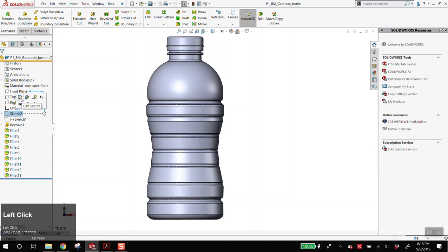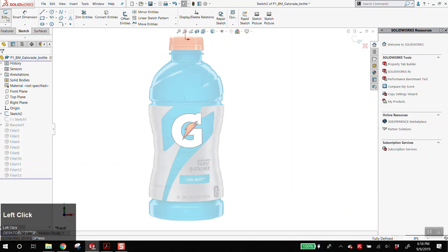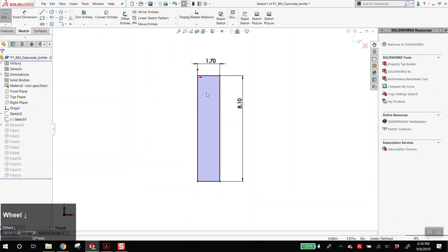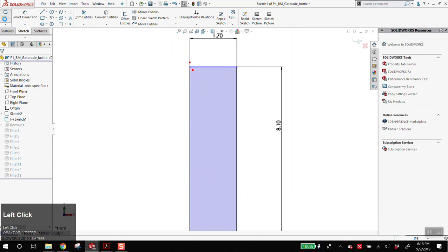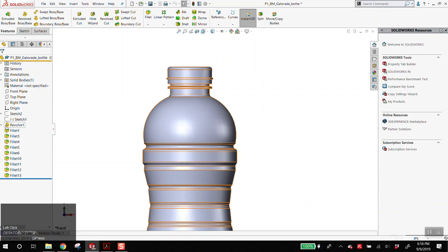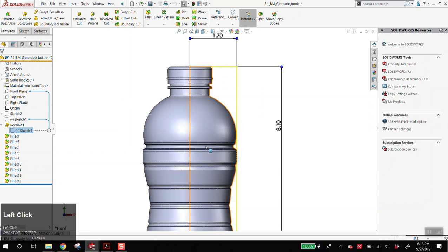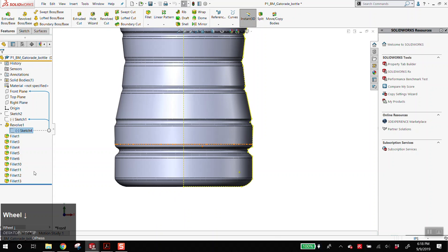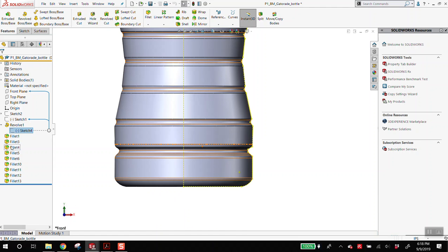So, okay, just a quick overview on everything. You got the sketch in there, looks good. Master sketch, are you on the origin? You are. Again, here's an instance. This is the same thing that Alec and Juan did, where you have the bounding box as your master, when really this amount of detail should be in your master. Does that make sense? So for you, you're also going to have to redo these fillets. The good news is, I feel like you shouldn't need this many fillets. Like a lot of these should be very similar in what the radius is.